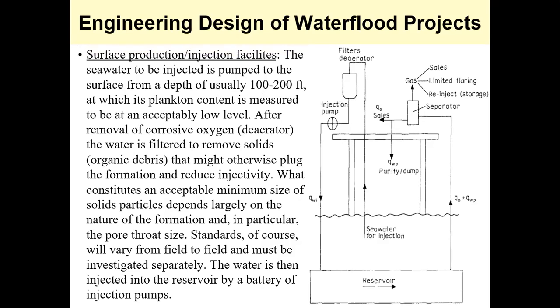So typically what goes down is that the seawater is pumped usually from a depth. So right there from the ocean, it's pumped to the platform, and then you check for plankton content, that's organic content, to ensure it's as low as possible so it doesn't cause biodegradation in your well.